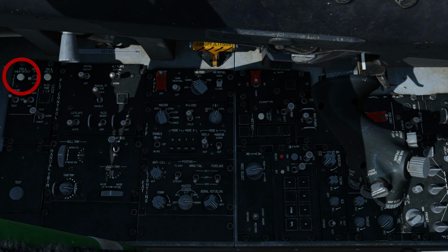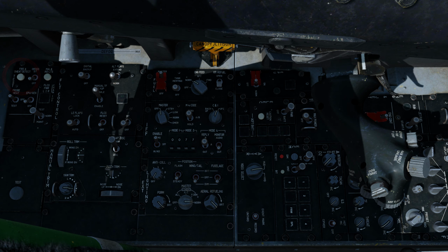To check continuity for the engine overheat and fire detection systems, place Fire and Overheat Detect in the test position. In the overheat state, the overheat caution light illuminates, and fire detection illuminates the engine fire eyebrow light. Overheat detection occurs 100C before fire detection. The lights and the master caution light are illuminated until the button is released.